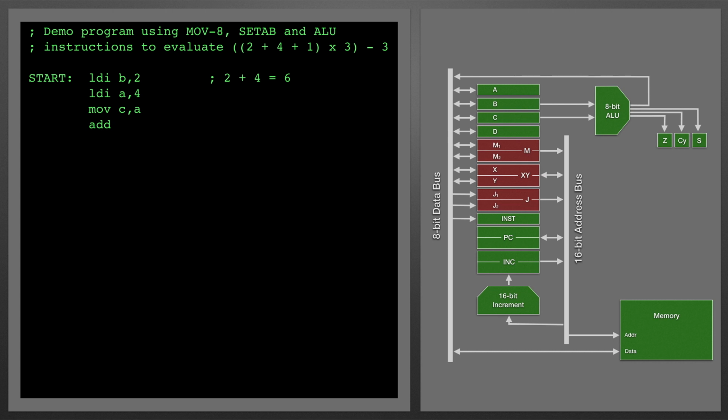Now this program is written in assembly style mnemonics that I specifically chose for programming this computer. Of course, this will all mean nothing to the computer, which is expecting a list of 8-bit instruction codes. And I'll take us through the process that takes this human-readable version of the program and converts it into something the computer can use.